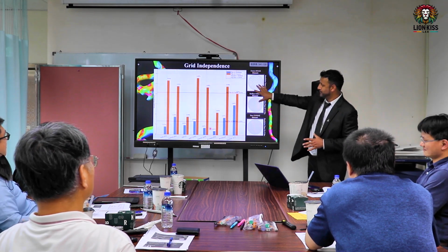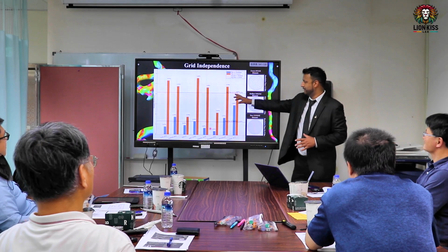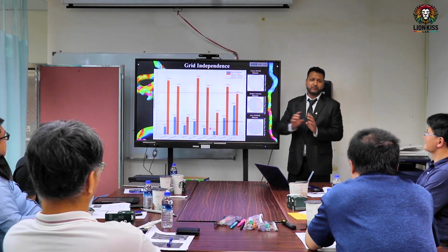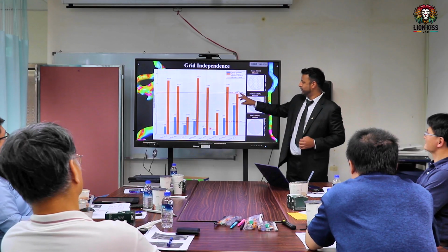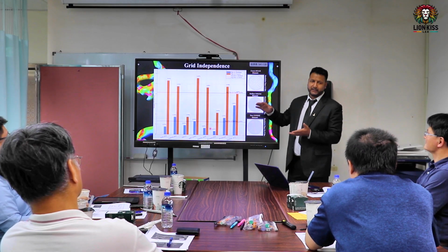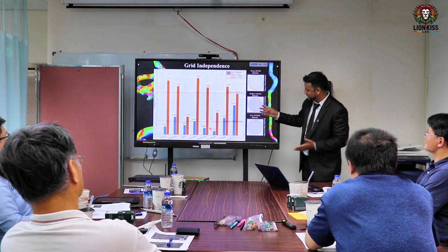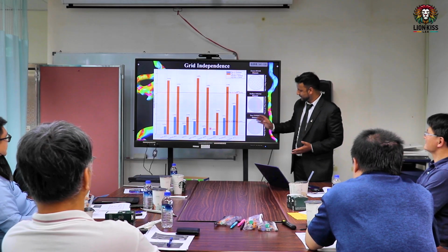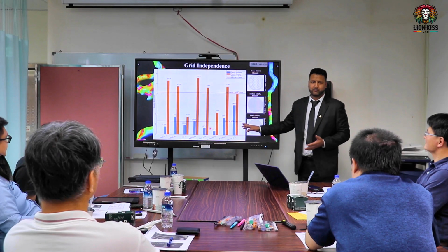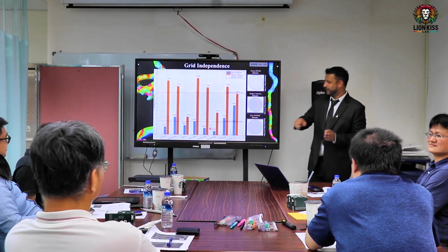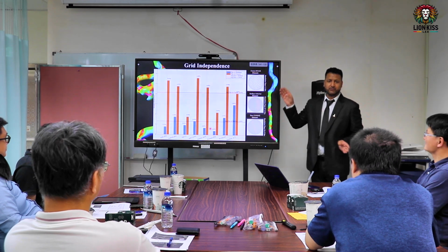When we check the meshing difference, when we compare the coarse one, the relative difference is very high, although it's less than 4.15%, it's still high. When comparing the medium and fine, the difference is only 1.3%. So it's not too much different. But if we see the time, it is so different.